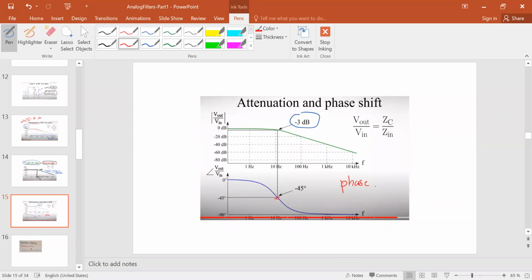So our biggest wish when we are designing an analog filter is that we want the phase to be linear phase, and I will tell you why I want that. So in magnitude, we want it to behave like nothing, and after this we have this slope, and then we increase the attenuation. But in case of the phase plot, we would desire to have a linear phase because we cannot have zero phase. The ideal specification has a zero phase part, but we cannot have that. So we will desire to have at least linear phase. We will not go for non-linear phase. So any filter with a non-linear phase is not acceptable.